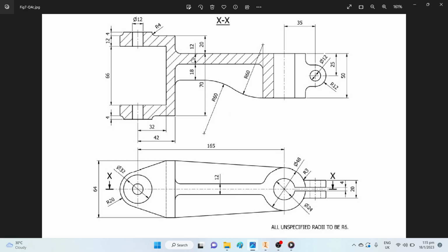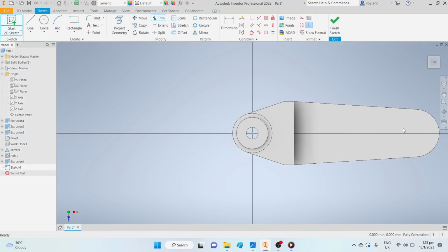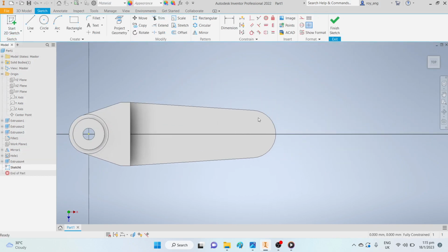It is 12 millimeters. After creating this whole profile, I will create the circular diameter 48, and I'll extrude it down by 50 millimeters. So what I do is I select from this top edge, and you notice how I select the top edge and not the bottom edge to extrude it, even though I'm going to extrude it past another solid, and that doesn't feel quite right, but it's okay because I'm following the dimensions that are stated in the drawing.